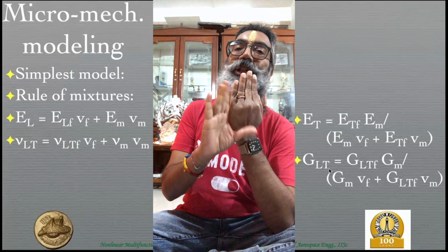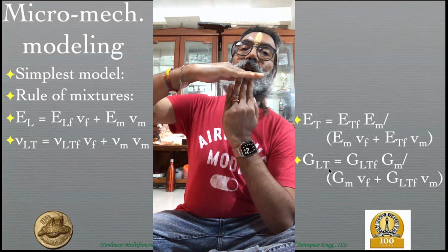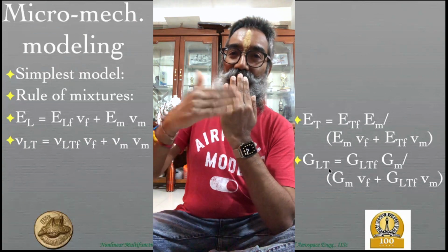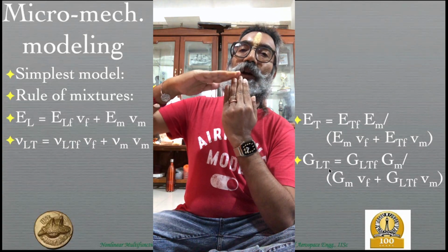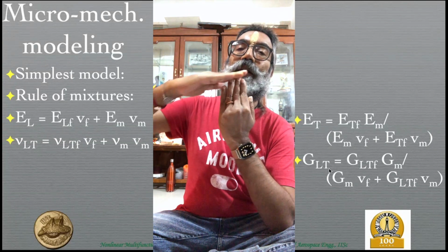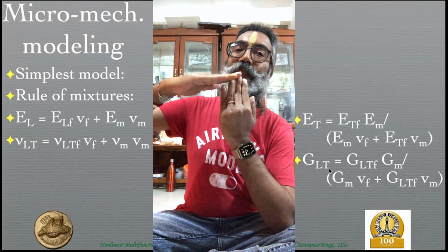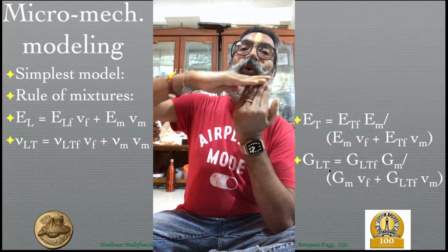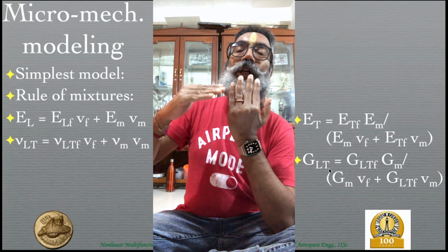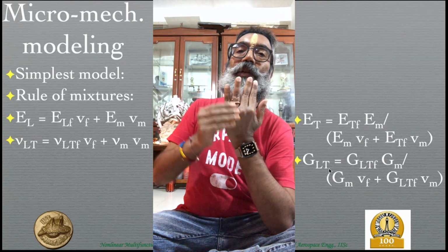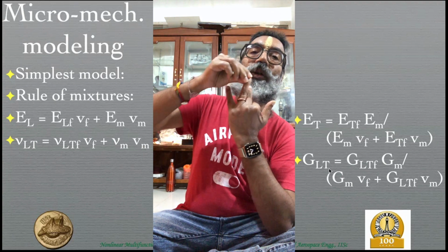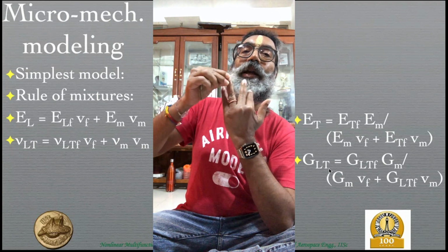Now, that change in right angle is going to be determined by how the material reacts with stresses and strains, in particular to the load that you're applying here in the form of a stress. So this stress is now trying to move this material in this particular direction, and now it's not just the matrix which resists it, because the fibers are in this direction. Trying to move a fiber like this through the matrix is going to be a little difficult.